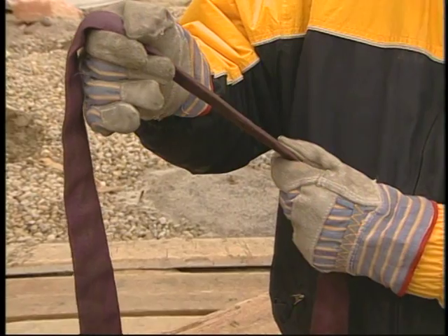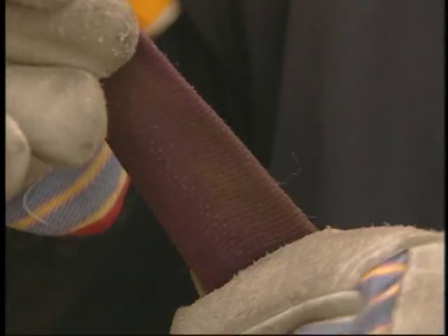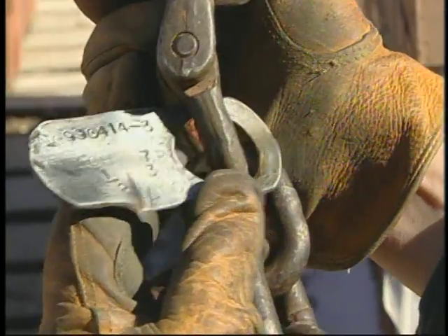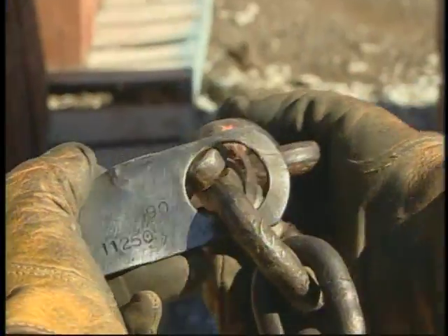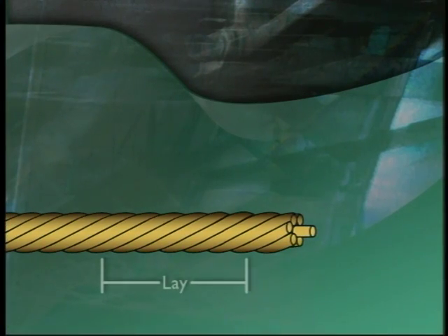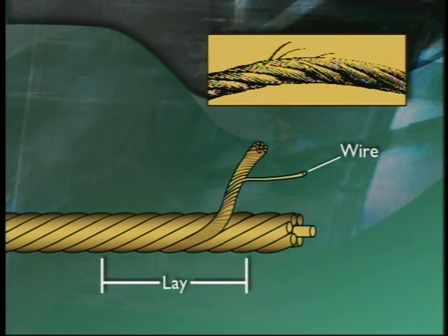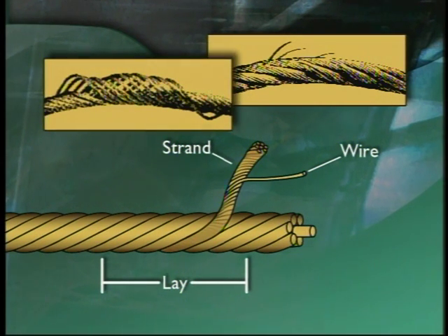Slings, fastenings, and attachments of handling and rigging equipment must be inspected for damage or defects each day before use. Alloy steel chains must have a permanent identification stating size, grade, rated capacity, and sling manufacturer. On wire rope slings, check the twists or lay of the sling. If 10 randomly distributed wires in one lay are broken, or 5 wires in one strand of a rope lay are damaged, the sling must not be used. You should also check end fittings and other components for any damage that could make the sling unsafe.